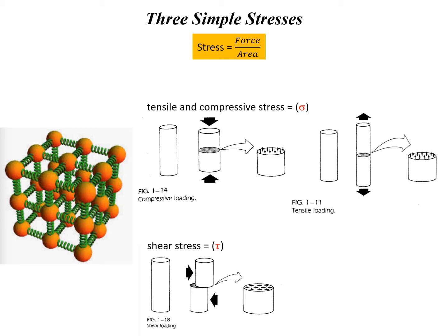And then if that stress is released, the atoms will spring right back to their original location. However, if you stretch those springs even farther, they start to get bent. And now when you release the stress, they don't spring back to exactly the same location. They're deformed. So what's really going on there is that the bond between one atom and its neighbors is actually breaking and reforming with different neighbors. So it might go back, but it's not going to necessarily go back to exactly the same shape.